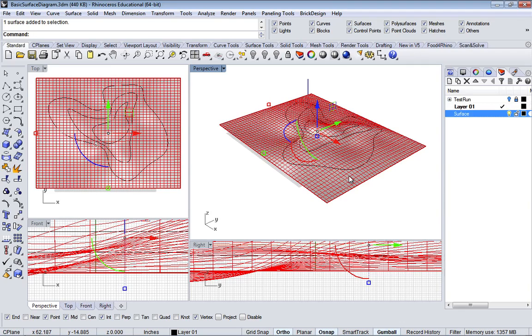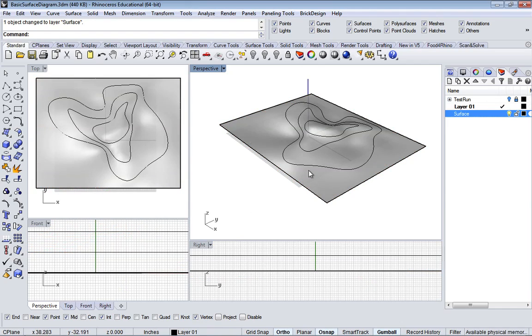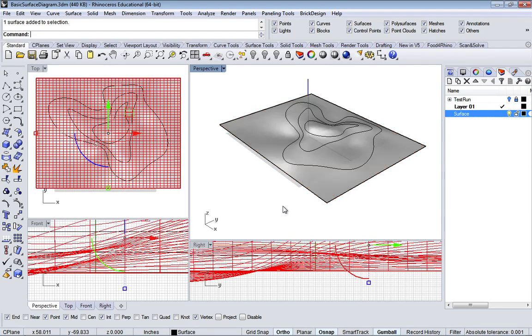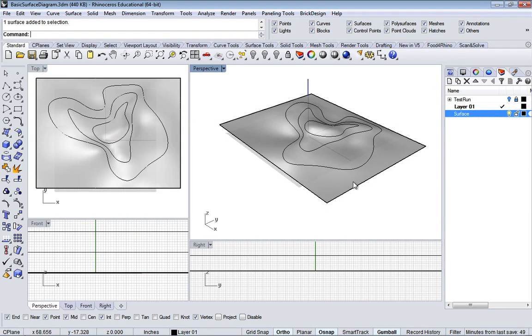So we've selected it. Now we want to move it onto that layer. What we want to do is come down here to the bottom, select where it says layer 1, and say, okay, put it on that surface there. When you select it, yours might turn yellow. I like the red myself, so I went in and changed the preference, so don't worry about that too much. But now this is on this layer, surface, and if I turn that off, it goes away. And I can now lock this surface, so I'm not messing around with that.